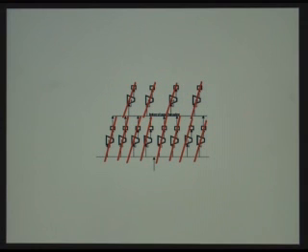I don't know if you guys have been involved in flare studies yet, but when suddenly all your production comes to a stop, that's a huge flaring event. All the gas that's in the facility has to go somewhere, and if it's not going to the ground, it's going to go to the atmosphere, and it goes out through a flare. So at the time, they had stack flares, and they had one that was for this facility, but it hadn't been sized in case of a complete shutdown like this, and so it got very hot and actually started to melt as it was flaring off this gas.